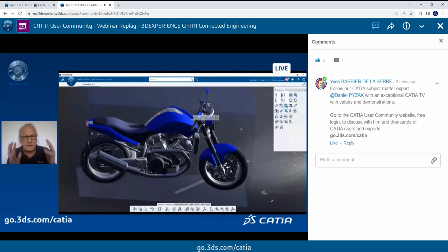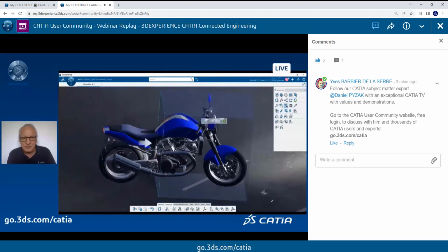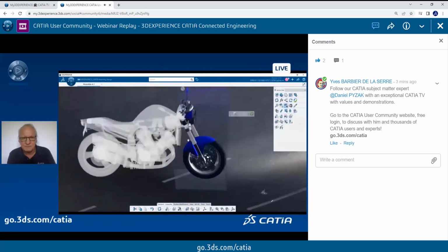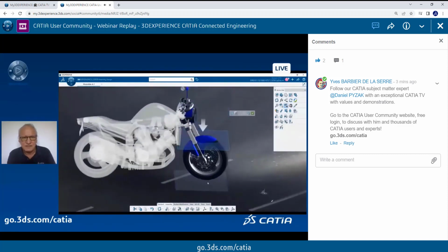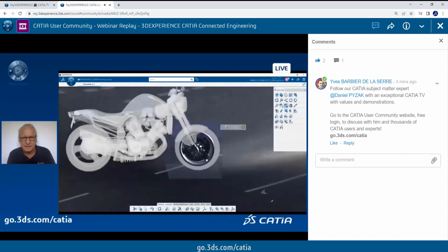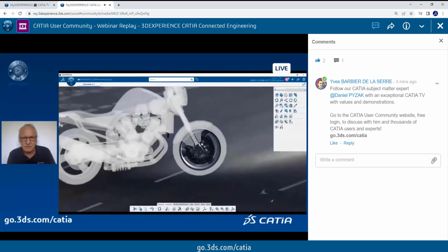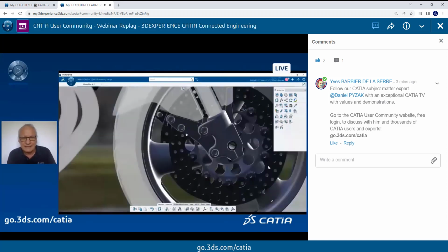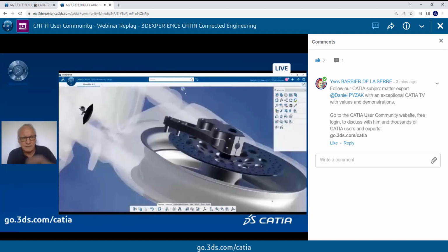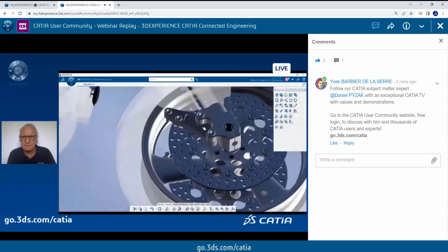First thing, I will select visually my context. I will define my working context, and you will see another nice capability of 3DEXPERIENCE CATIA, which is the display of what I don't need in a ghost way. So what you see in dimmed or transparent white is in fact in ghost mode. But at least I know where I am in my full assembly.